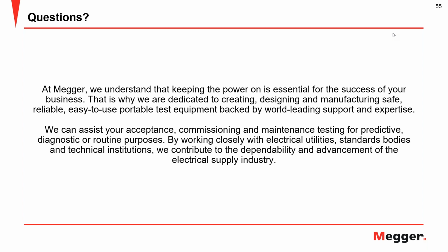The second point: after it was found that DC causes damage to solid dielectric cable, there were also investigations on how good a DC hypot test is in finding and bringing certain types of faults to a flashover. While the AC did very well on these tests, finding a lot of faults that were introduced to the test samples, the DC did not do very well.